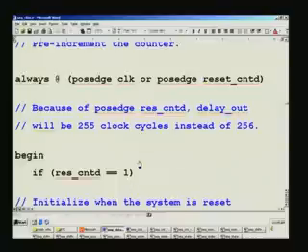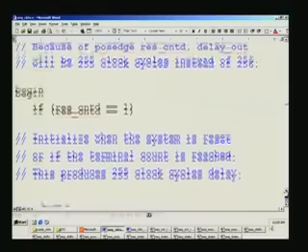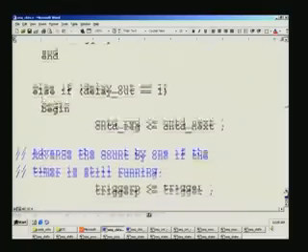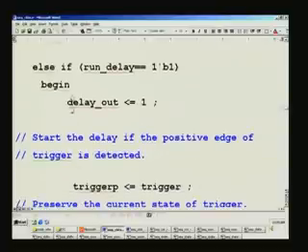In the earlier way of representation, this has been separated out, this power on reset has been dealt here, and the actual counter reaching 255 had been dealt somewhere here in between. So it added one more else if, thereby slowing the system, and also instead of 255 set point we got 256. The reason being that when it touches 255, in this case you would have very easily seen that 255 clearly for one complete cycle.